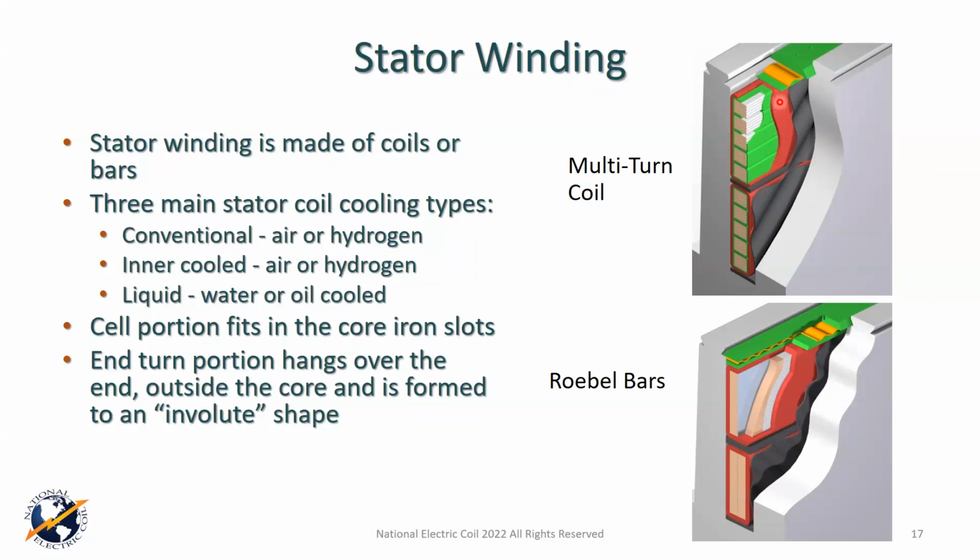In more modern times, in the latter part of the 20th century and the beginning of the 21st century, there have been some machines, especially some coming from Asia, that have run volts per mil as high as 80 or 90, which is extremely high, to the point where a lot of domestic manufacturers say we'll have to derate that machine to rewind it. We won't be able to maintain that rating reliably. So volts per mil matters.